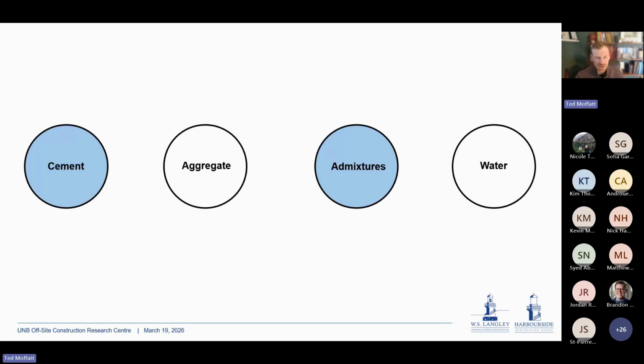So if we elaborate a little more on mix design, a given concrete mix is essentially comprised of the following four constituents. Obviously, we need cement and water to hydrate together to form the glue that holds the aggregate together. And admixtures, as I said, if we have concrete exposed to freeze-thaw, we need air in it. There's a lot of novel, incredible admixtures out there, whether it be shrinkage reducing, superplasticizers, water reducing, or viscosity modifying admixtures, really depending on your application, if you're placing concrete underwater or architecturally or SCC. There's a plethora of admixtures available to essentially give you whatever elastic properties or plastic properties you want in your mix.